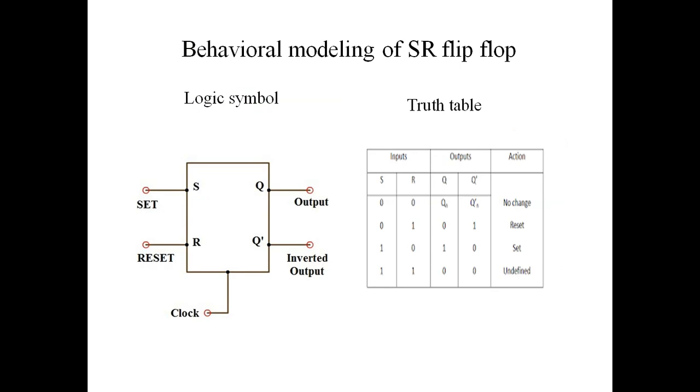Next, modeling flip-flops. In that, first one is behavioral modeling of SR flip-flop. We will see how to write Verilog code for SR flip-flop using behavioral modeling. Behavioral modeling is the highest level of abstraction in Verilog HDL. We can describe the circuit by just knowing how it works.